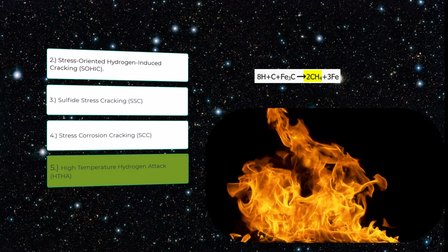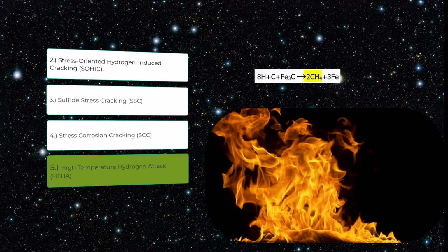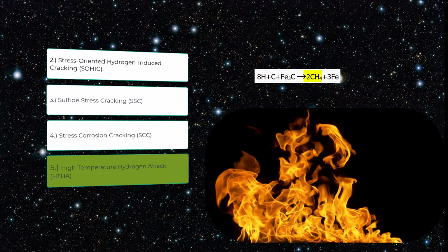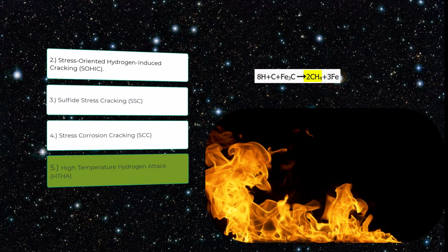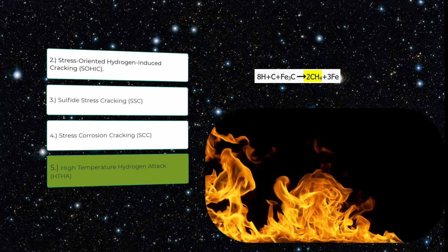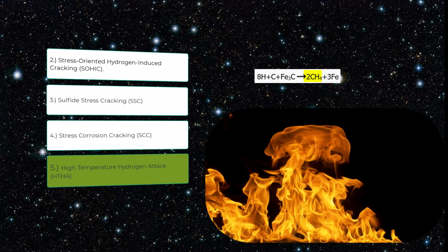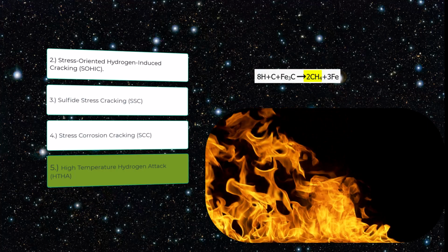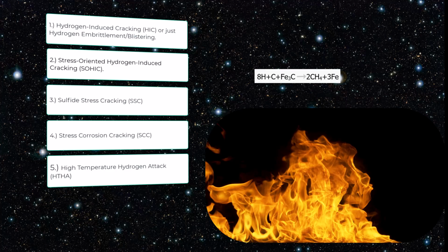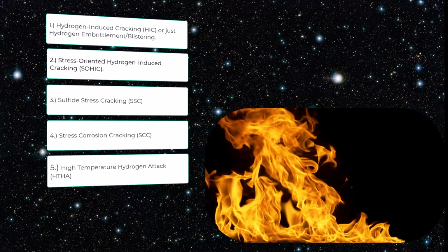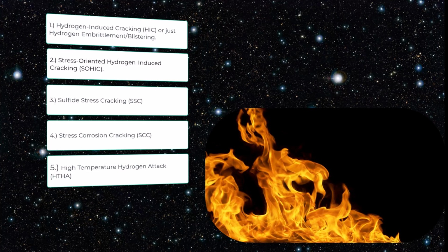And that methane gas does exactly what the hydrogen gas did in the dislocations, this time at high temperature, but the presence of gas continuing to expand and pressure up these voids causes brittle fracture. Same thing. This concludes this Tech Talk on hydrogen damage mechanisms.